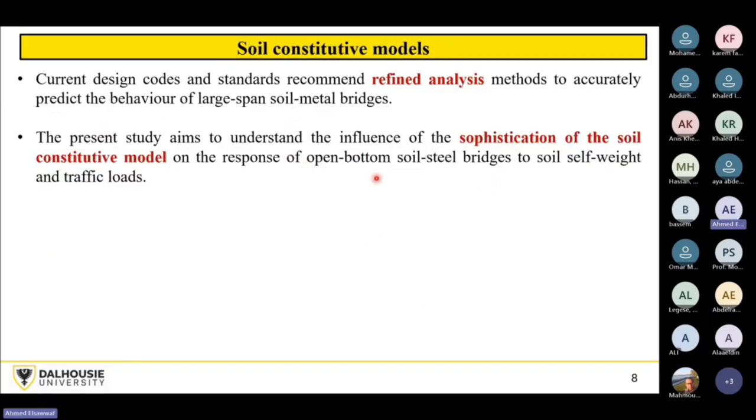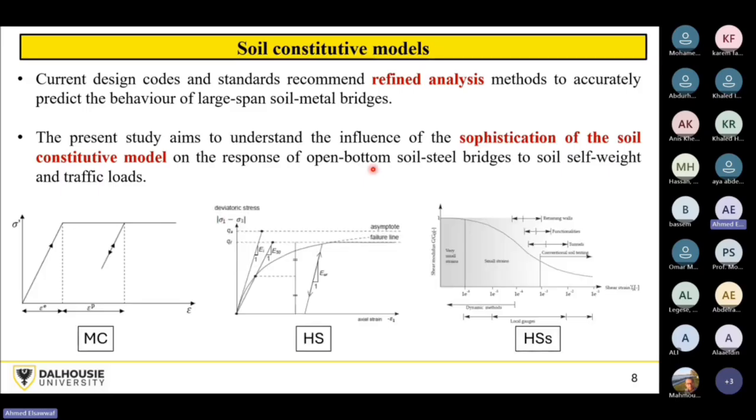So before going deep into my presentation, the last piece of cake in my introduction is the soil models that we can use in Plaxis. Here you can see that we have 3 popular material models: the Mohr-Coulomb model, the Hardening Soil model, and the Hardening Soil model with Small-Strain Stiffness. I just want to give, in 1 or 2 minutes, a quick introduction to the main basics that may affect our model. The Mohr-Coulomb model is very well known, and it features a bilinear stress-strain curve.